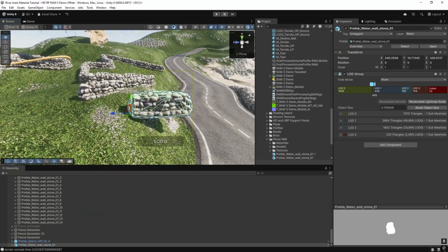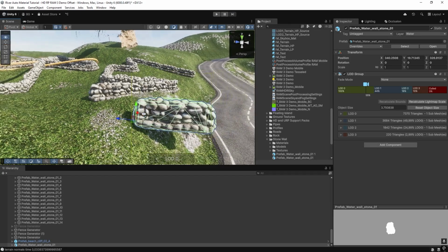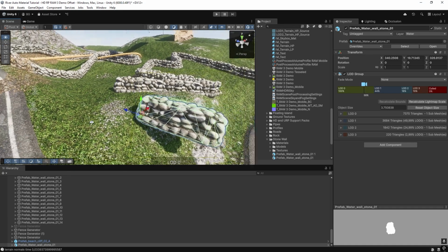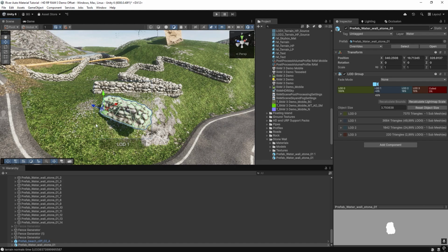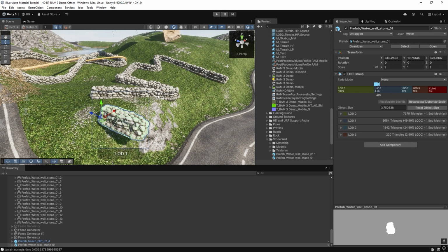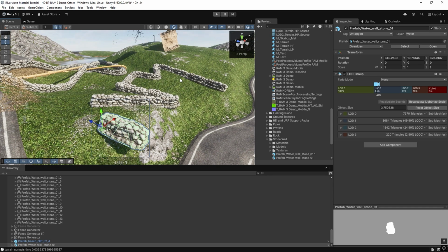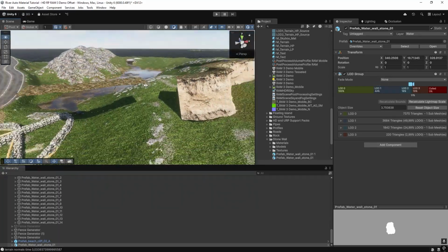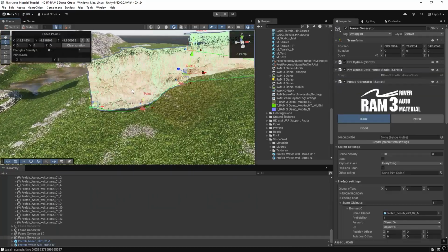Of course, this is a very bad example because none of the prefabs should have a minus z on the forward axis, but we did this with the idea to show you that you have to set up this value if you have a mesh that doesn't fit normal axis directions.